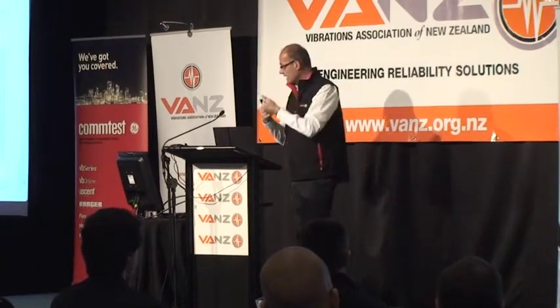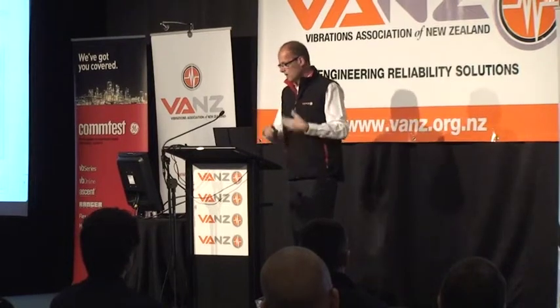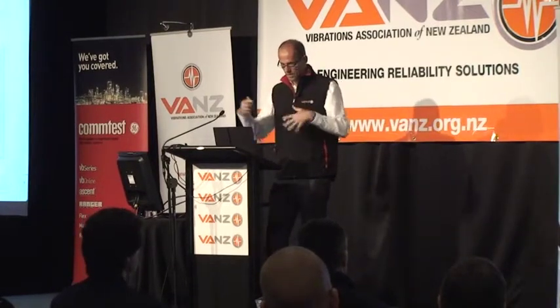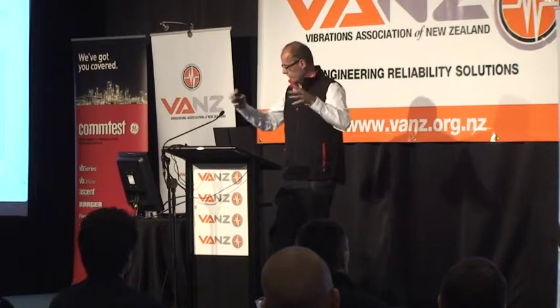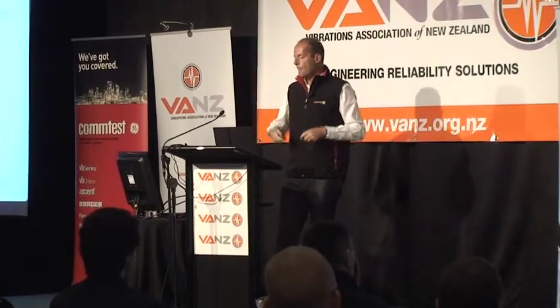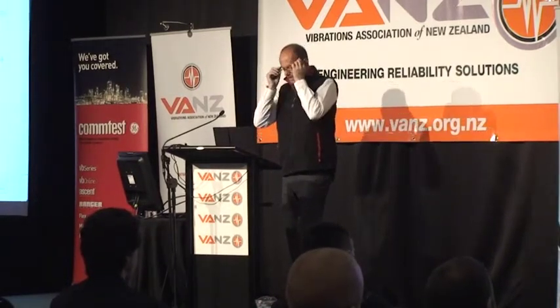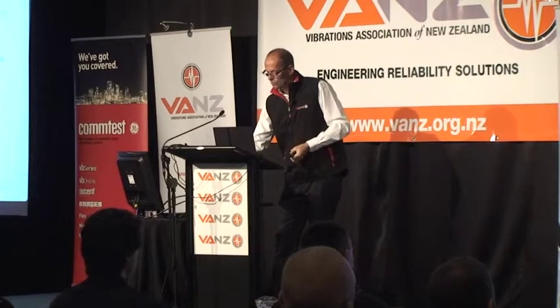But if I had angular misalignment, then there would be more axial vibration, and so we need to measure in 3 axes if we can. Somehow we need to get the whole story from the machine, the really high frequencies, the low frequencies, the works. So anyway, we put the sensor on the bearing, and we can then look at the individual frequencies.